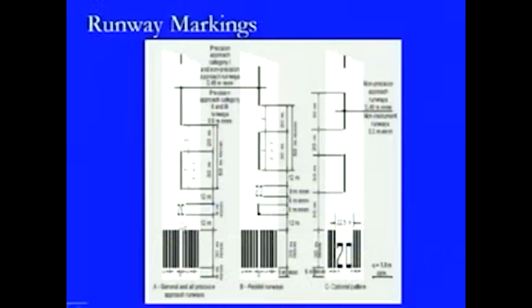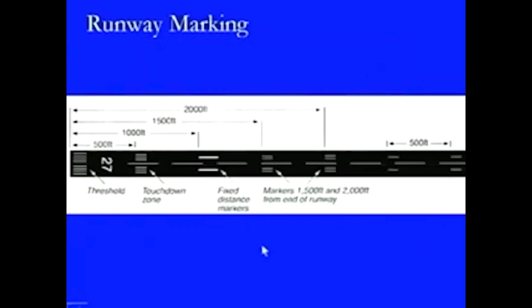These are the things which have been shown here. There are a number of different ways by which this marking can be shown, like 20 being defined here, it is 9 meters long in this form. So, this is 9 meters long. Another way is the 20 L condition. So, 20 L can be written as 20 with L at the bottom, or it may be 20 and L in continuation. Those are the two ways by which it can be done. And the third way is that we can use this 20 within the threshold markings. So, there are different ways by which the runway markings can be provided.